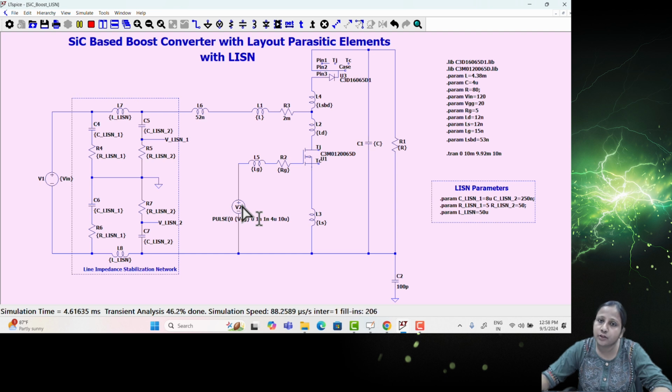If the noise level is high, you will need a higher value of the filter, with higher attenuation level, but that will also work at lower frequency. So you can design the filter at maximum frequency. Anyway, it will work at lower frequency, where the noise level will be much less, and you already know why. Accordingly you can design the filter.